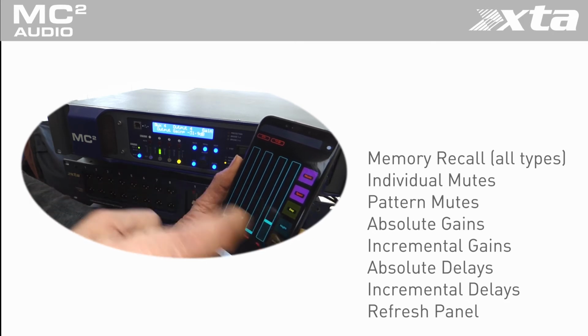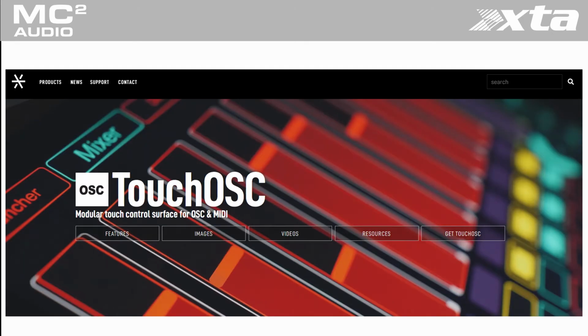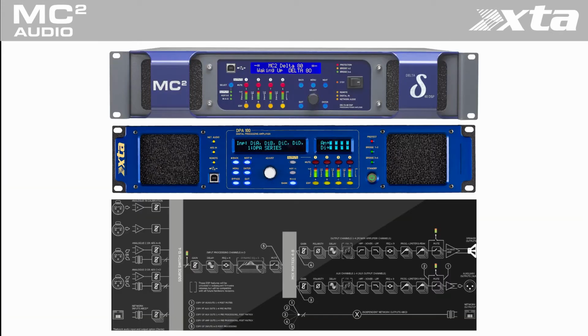We are going to design the panel in the Touch OSC software from Hexler and deploy the panel on a smart Android or iOS device. We will configure an amplifier and smart device to talk together. We will use the DSP built into the amplifiers to switch between a music playback source and a satellite sport channel. All the speaker management, speaker protection, source switching and room EQ is done by the amplifier's built-in DSP. The control panel could be deployed in a wall-mounted Android or iOS smart device running Touch OSC or simply a manager's phone.